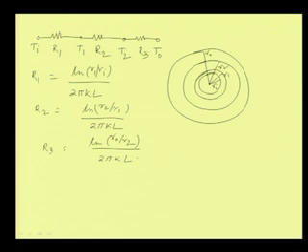And then, what will be the rate of heat transport? As in the case of plane walls, we can write down that expression. Q dot is equal to T I minus T 1 by R 1, and at steady state all the things will be similar.